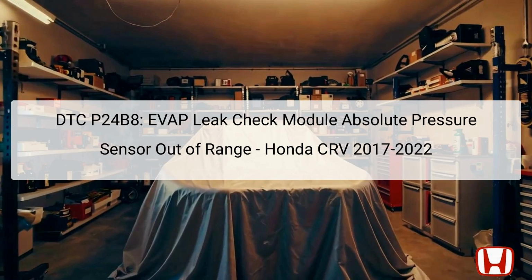If P24B8 is stored alone, begin troubleshooting specific to this code. However, should you encounter it alongside codes P24BA or P24BB, prioritize diagnosing and resolving those first, as specified in the diagnostic protocol. Remember, operational verification and a thorough understanding of the system's normal parameters are vital before any repairs are attempted. The EVAP Leak Check Module is essential for maintaining the integrity of the EVAP system by detecting leaks in the fuel system and ensuring that fuel vapors are contained.